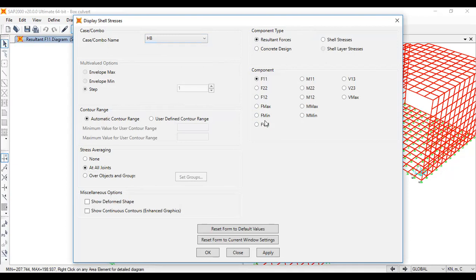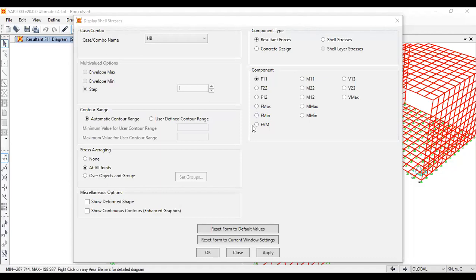You combine those things and it gives you the von Mises stress, right? So these are M11, M22, M12, the moments, right? And these were the principal moments, right? So shear components, this is, as I remember, transverse shear maximum, right? And now you know what these are, right?